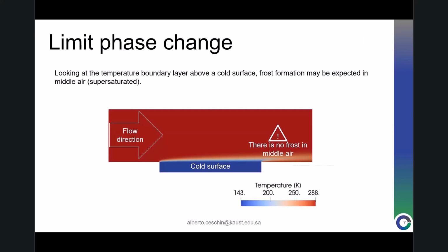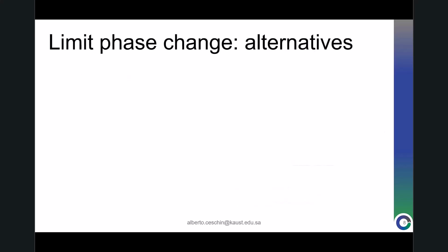There's a little catch if we look at a flow, for example, on a cold surface. If we look at the temperature profile, we see that we could be under the sublimation point also in mid air, but of course we don't have frost formation in mid air. So we need to somehow limit our phase change. And there are two approaches in literature, always for water.